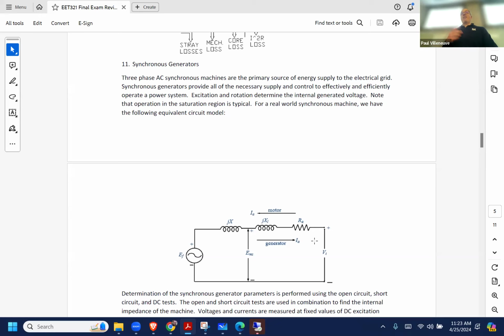Now, PV or wind is catching up, but there are some problems with that because when we have synchronous generators, we have hunks of iron. We have mechanical systems that are driving that. And so when faults occur, the energy is extracted out of those over time. You can't get a solid piece of mass with all this inertia to stop instantaneously unless you're pulling out a lot of power. But in a PV system, there is no inertia. It's just light being converted into electrical energy. So it's very easy to take the power off.